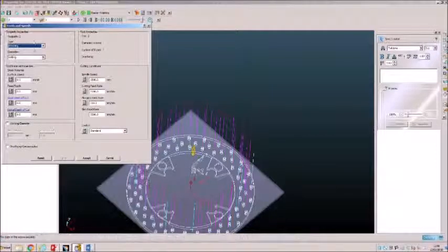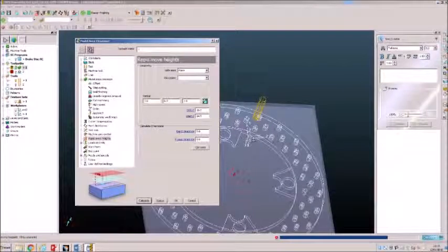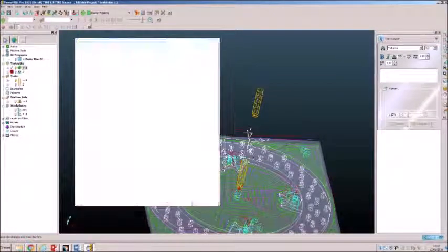The feed rates for both of the processes were changed to a suitable value. A safe rapid move height of each tool was then changed to 5mm above the surface of the block.